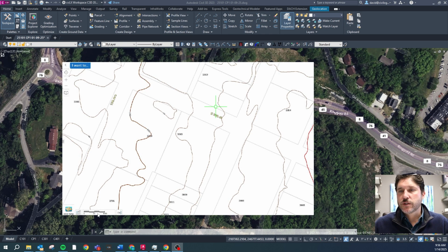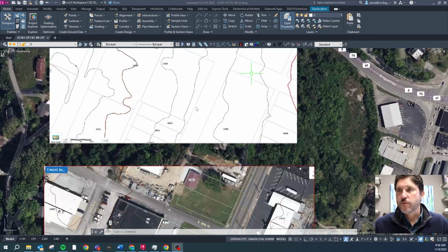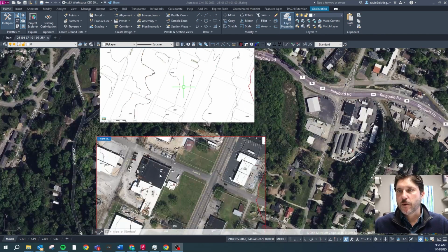I can use the scale, but I also know that yesterday I lined one up from this Hamilton County GIS and the scale came in a little bit off, so I don't really trust it. So what we're going to do is I printed the tax map and I printed one with an aerial as well, and then I'm going to line it up based on the aerial, and then we can line the tax map up with this one.